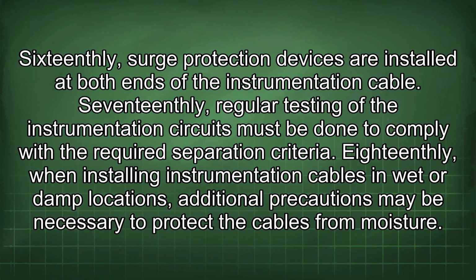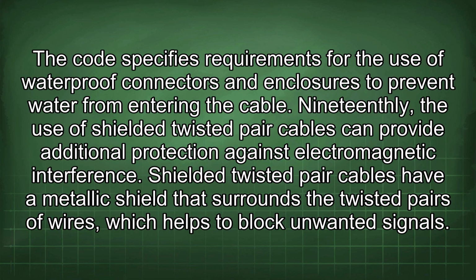18thly, when installing instrumentation cables in wet or damp locations, additional precautions may be necessary to protect the cables from moisture. The code specifies requirements for the use of waterproof connectors and enclosures to prevent water from entering the cable.